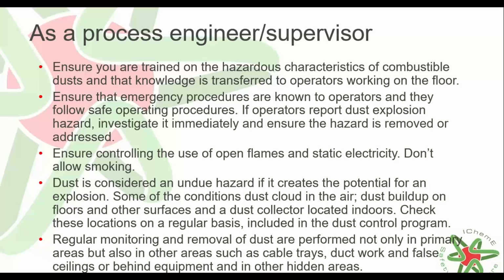Make sure that regular monitoring and removal of dust are performed not only in primary areas where dust accumulates, such as on production floors, but also in other areas such as cable trays, ductwork, false ceilings, as well as behind equipment and other hidden areas that you may think about in your operation.